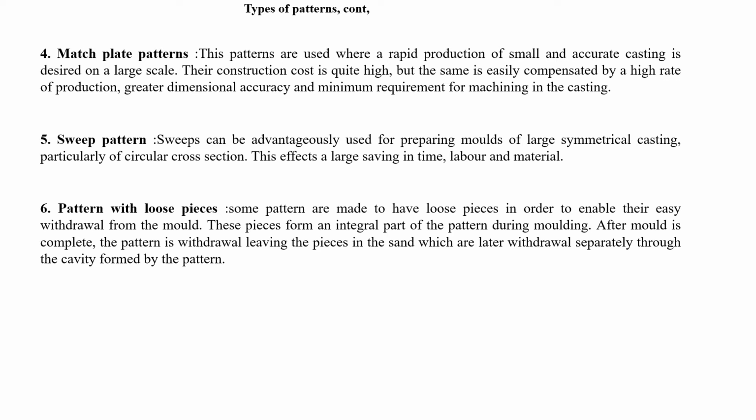It means it is used when we do not want to do much work after it is completed. We have the sweep pattern. The sweep pattern is used when we need a large symmetrical casting of circular shape or circular cross section.